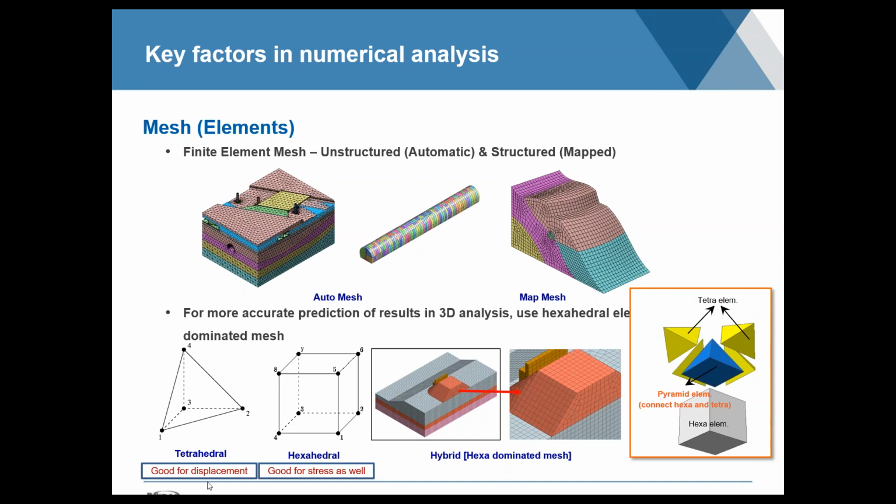The other features about GTS is we have options for the shape of the 3D element you want to choose between tetrahedral and hexahedral. They both have their benefits. The hexahedral option ends up being more efficient in terms of number of elements. It ends up having fewer overall elements than tetrahedral when you mesh, let's say, the same geometry.